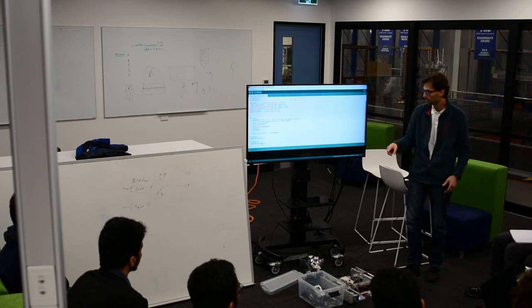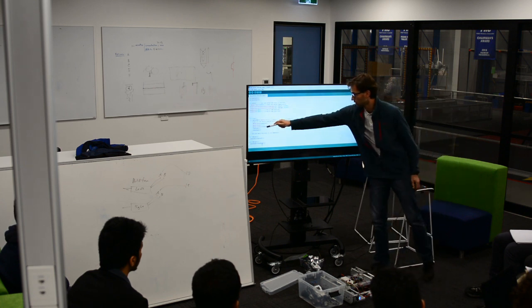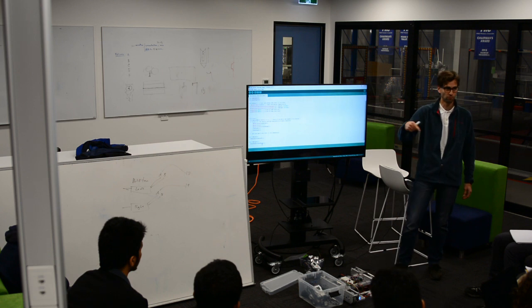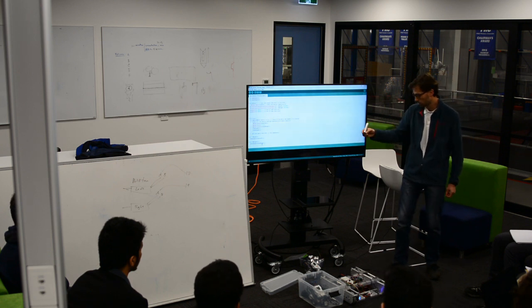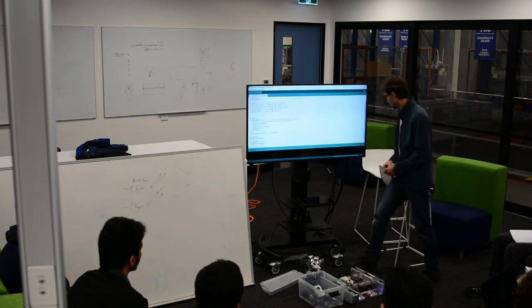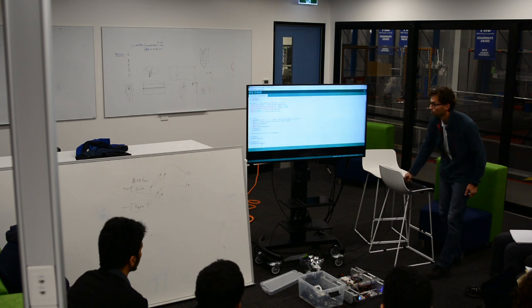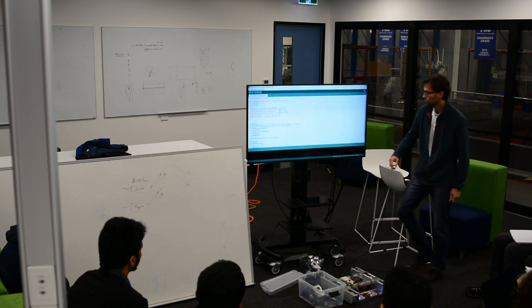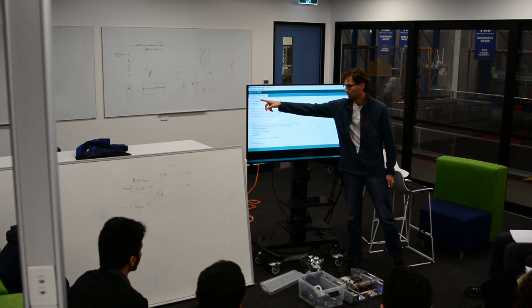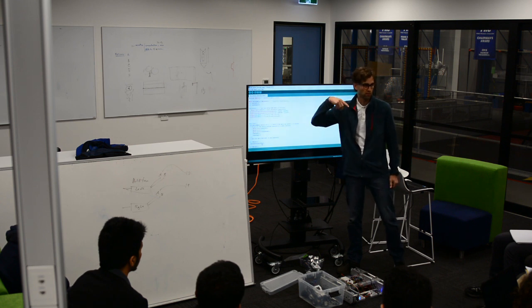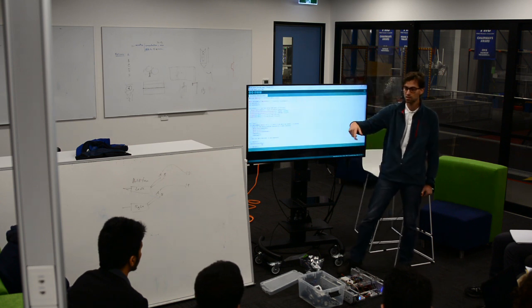I want to get some feedback on that, and I could put in my loop that I want to talk to the serial port really, really rapidly, but I didn't want to do that. So I used a library or a function called Metro, and Metro is a way to schedule events. So like a train, like the Paris Metro comes every 10 minutes.